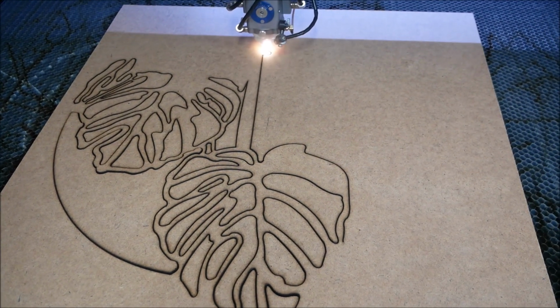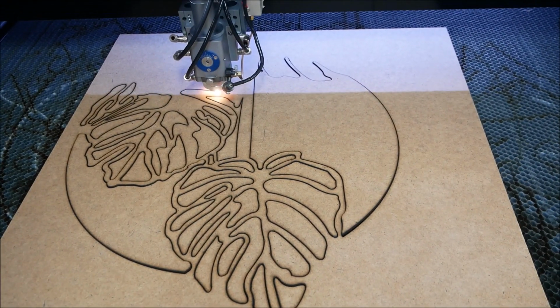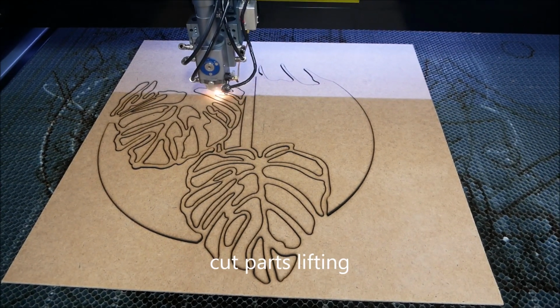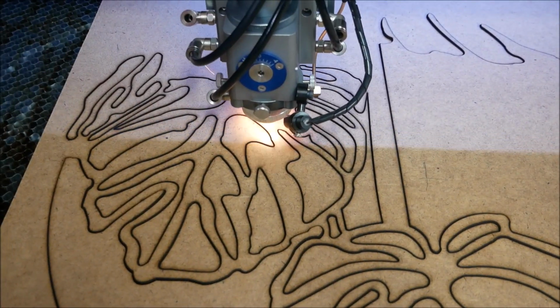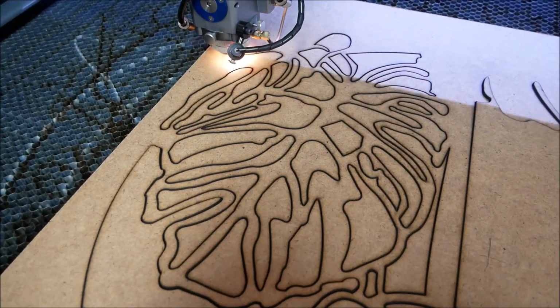The cut's coming along quite smooth. What I check here is that the odd piece lifts up a bit, and that tells me the laser settings are correct. This 1/8 inch hardboard is fantastic for cutting. It's very smooth, a very detailed cut.